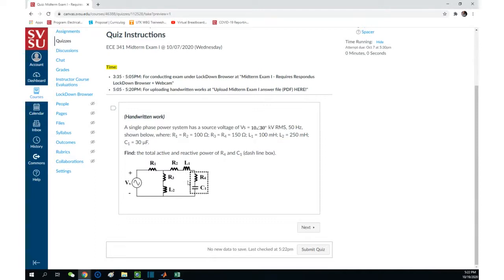So you have voltage or current. You don't have to have both because you know the impedance easily, right? You use the impedance times the current magnitude squared, or the voltage magnitude squared divided by the impedance conjugate. Either formula should work.